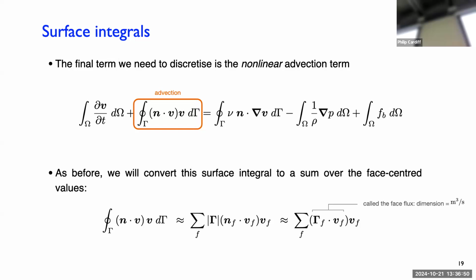The area vector multiplied by one of the velocities represents a volume flow rate, meters cubed per second, and they sometimes call that the flux. So often they mention fluxes in finite volume methods. It represents a flow through a face. So if you say flux, they're normally referring to this mass flow rate or volume flow rate in this particular term.